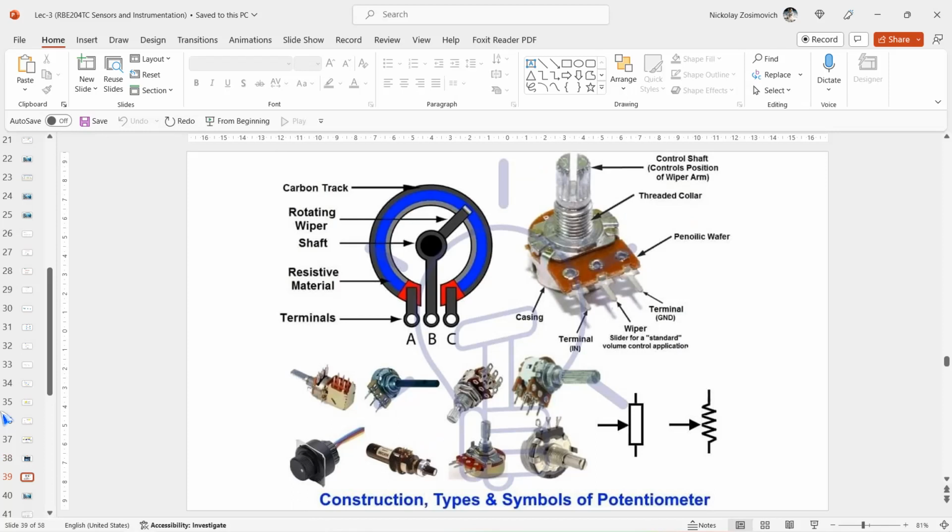By a special construction or material choice, resistors can be made useful for sensing various quantities, for instance, force, torque, pressure, distance, angle, velocity, and acceleration. After having defined resistance and resistivity, we discussed successively potentiometric sensors, strain gauge, piezoresistive, and magnetoresistive sensors.